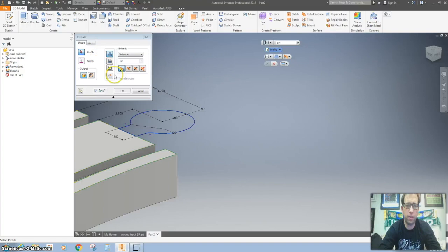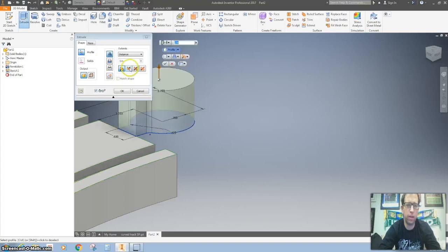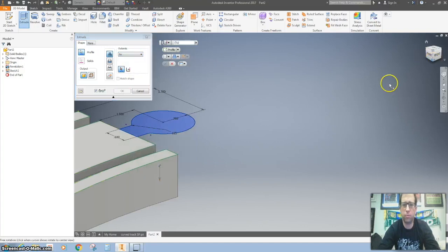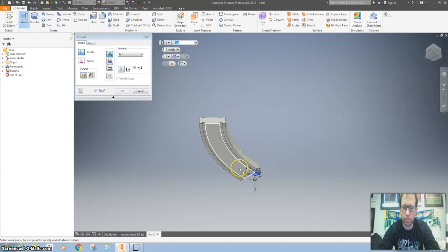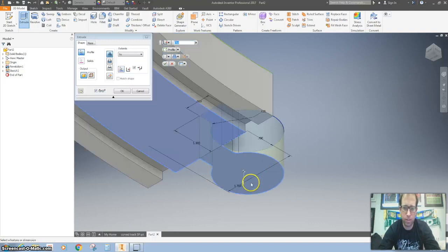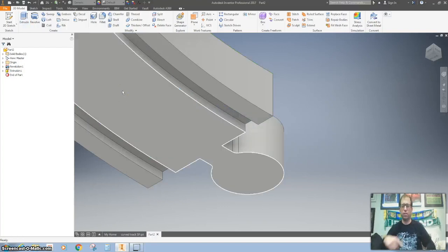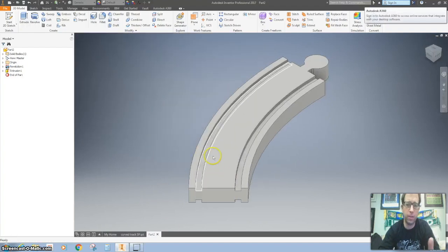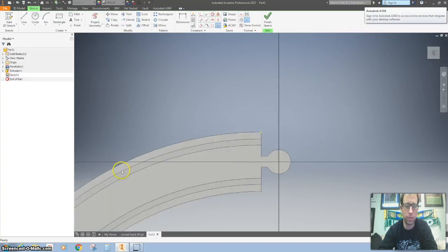Finish that, hit the extrude, click on that. We need to change the direction. I'm going to go to 2. I'll flip it over a little bit and just click on the bottom edge. I'll take it right to that, just in case we ever change that dimension, that will change also. And now we just simply need to take away that part down there. So this one's going to be a little bit trickier.